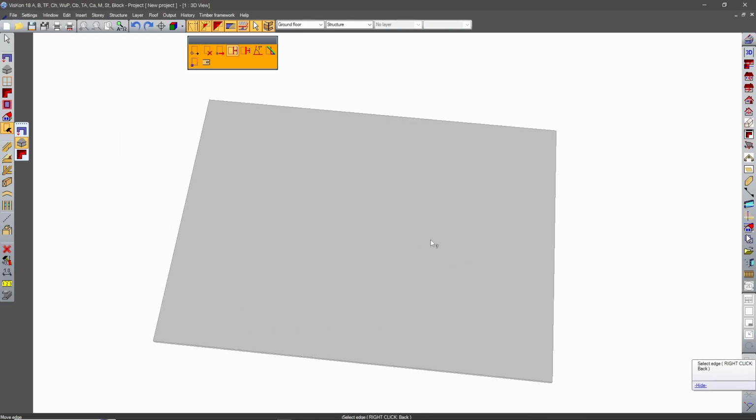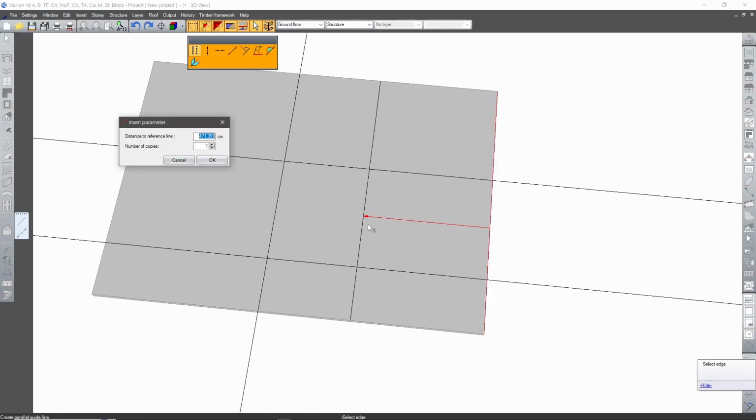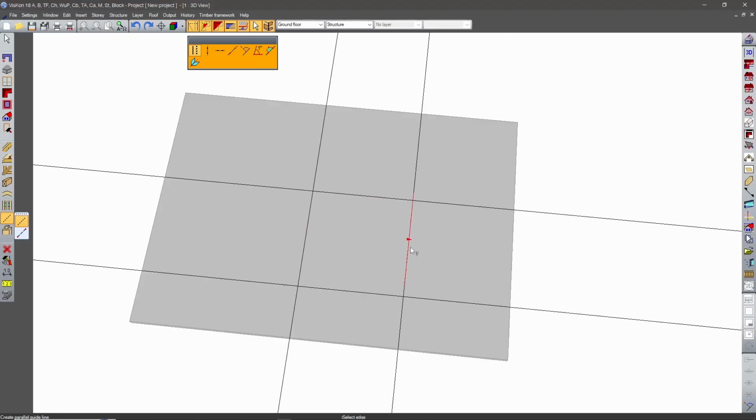And the H shape is kind of laying down, but I'm gonna show you what I mean. This portion will be 4 meters. This one is 2. Here we have 6 meters. And here, 4, sorry. And here, 4 meters. Now, let's do a modification. Again, plug in, create a null slab, move the portion, click on the edge, define the segment, and extend or retract it.